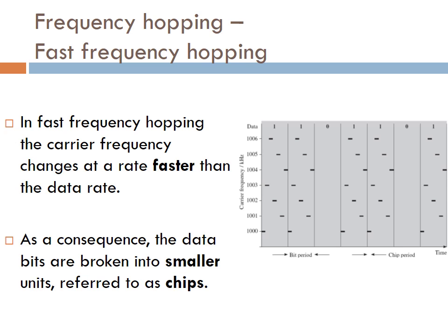There are different ways of describing what is happening here. For some purposes, it's useful to think of the whole hopping pattern during a data bit as a single symbol. One symbol is then made up of 7 chips in this case. This is a viewpoint that should be adopted most of the time.